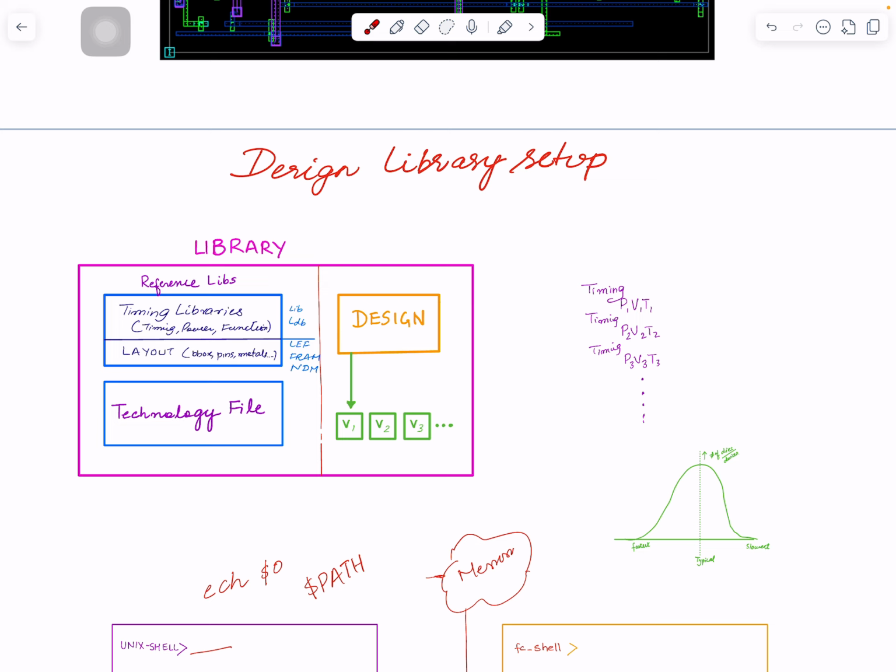That's why, though I didn't explain the topic of variations, voltages can be different, temperatures can be different, and process can be different. What is the process? Let's say it's 180 nanometer. It's the same process, but some of your transistors or dies, overall transistor plus interconnect, can have faster characteristics compared to others.